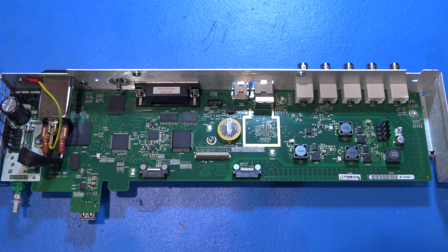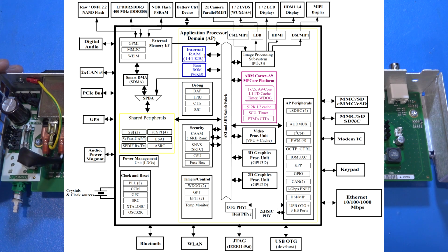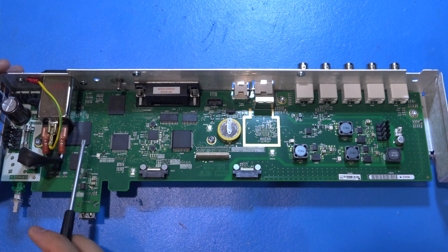And here is the main digital board. This is where the application and the firmware and the LCD control and everything is going to be. This is also the interface to the user. So if you look carefully here, you can see this chip. This is an NXP dual Cortex-A9 ARM processor with a lot of other peripherals built into it, essentially a multimedia processor, industrial applications included, and this is running at about 800 megahertz.